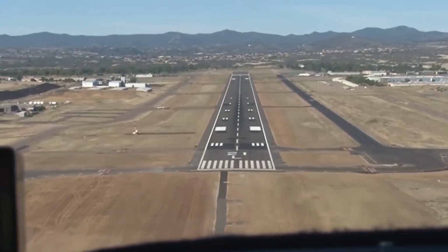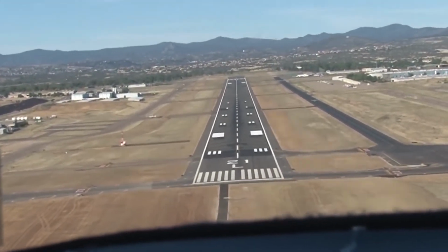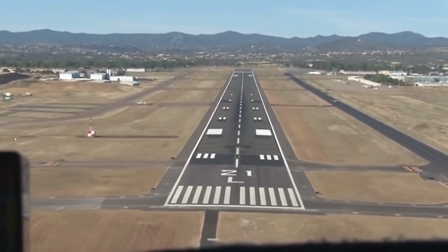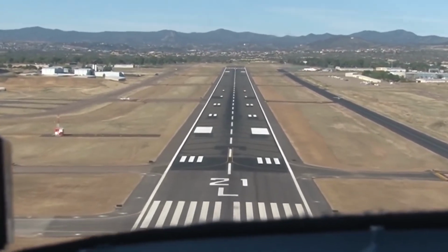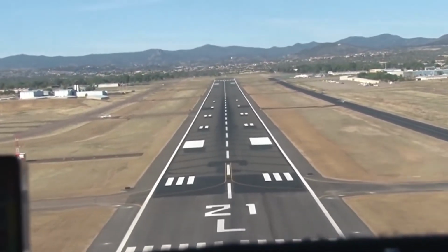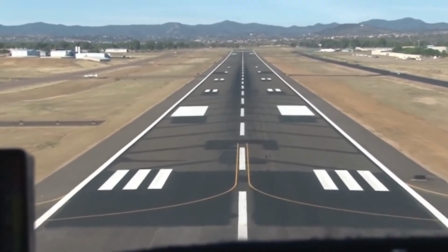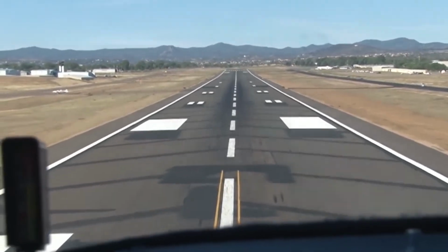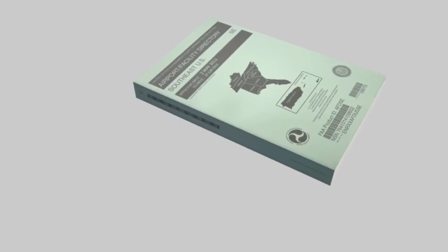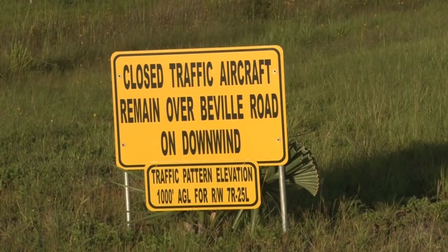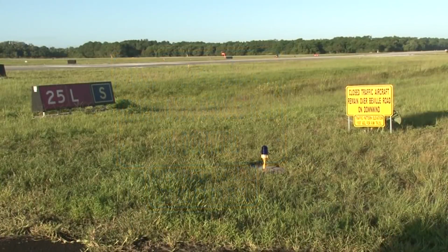As airports become encroached by homes and developments, the pilots and airport operators may have to deal with noise complaints. At some airports, the pattern procedures may be amended to minimize the overflight of the more noise-sensitive areas. Nighttime curfews or restrictions to training activities such as touch-and-go landings during certain hours may also be in effect. To find if noise abatement procedures exist at an airport, you can consult the AFD or similar publications. When noise abatement procedures exist, informational signs outlining recommended procedures are often posted near the departure ends of runways.